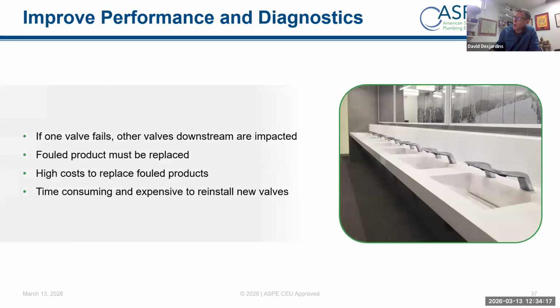The other place that you might see cross flow, and I went through standard point-of-use mixing valves. All of those, per the standard ASSE 1070, have screens and checks on them, right? That's great, because hot and cold come into any mixing valve, and you want to make sure it doesn't go from one way to the other. Now, you might have a building with hundreds of these. If the check valve gets fouled, for example, that's a perfect place for hot to go into cold or cold to go into hot. Finding that, you'll pull your hair out. And ultimately, it's very time consuming.